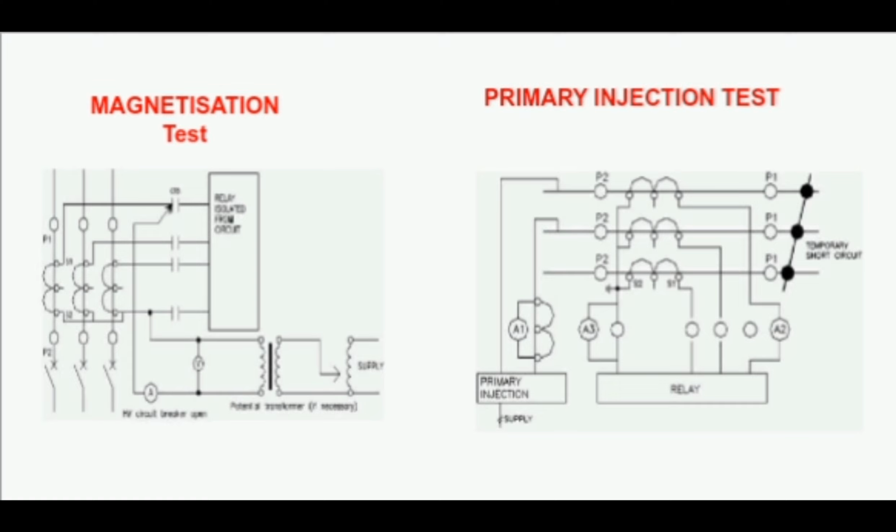Single point grounding shall be verified for CT circuits before starting this test. Inject 25% of rated primary current between one phase and earth with all burden connected. Measure secondary current at all points of the CT circuit. It shall be done for the other phases as well.